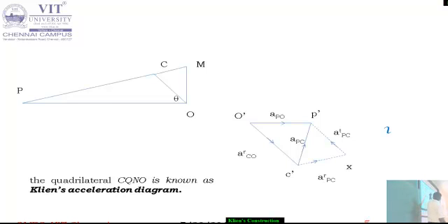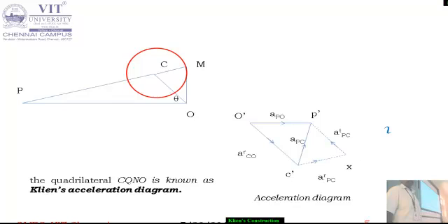Okay, so both red and green intersect at two points. Join those two points and extend until the horizontal line OP. Okay, so like this. So this is KL, the intersection points. Join KL and extend till the horizontal line. Okay, so that point may be taken as N. So now what you have to do, join N with C.